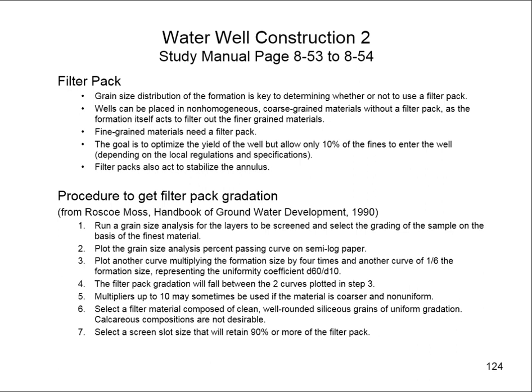So when we looked at the formation itself, we had a lot of stream gravels, and it's very heterogeneous. So we decided not to use filter packs so we could sort of see the natural situation. And the goal here is not to have so many fines being drawn into the well that can damage your pump or impact the development process.